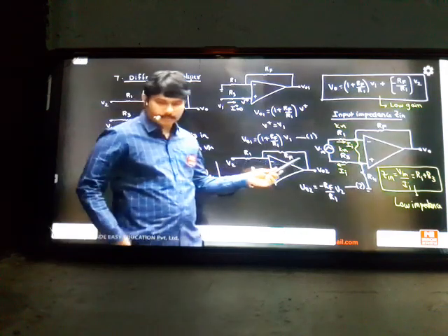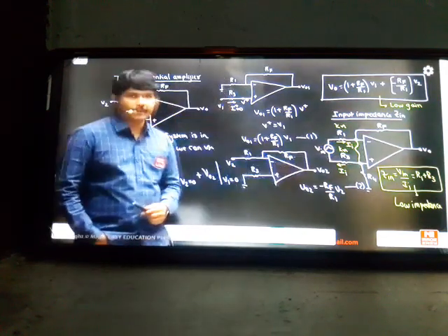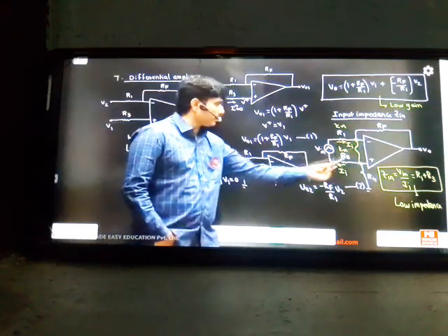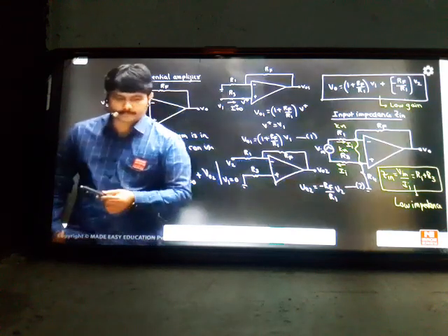Input impedance, nothing here. Who is this? Divya Das. I made these two a virtual short. When you virtual short, this is a closed loop, so this current will go in series in the loop. So R1, R3 will be the input impedance, R1 plus R3.